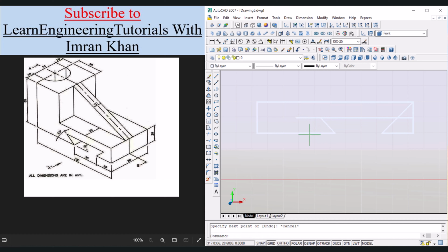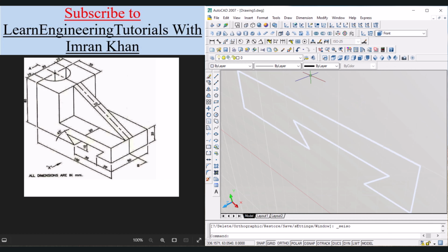Now we have to use trim command, so TR, enter. Click on this line, click on this endpoint, and click over here. Press escape. Now this object is complete. Click on SE isometric. Now we have to use press pull, so click on press pull icon, bring the cursor over to this area, and we can see that press pull is not working.